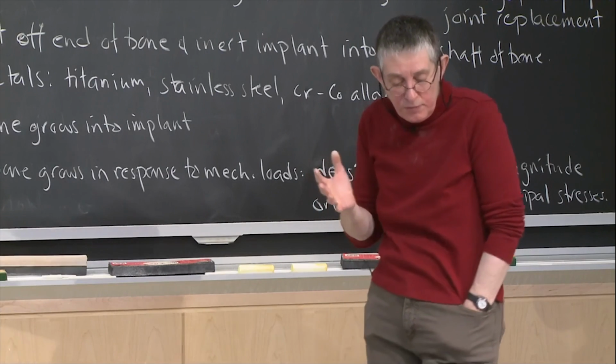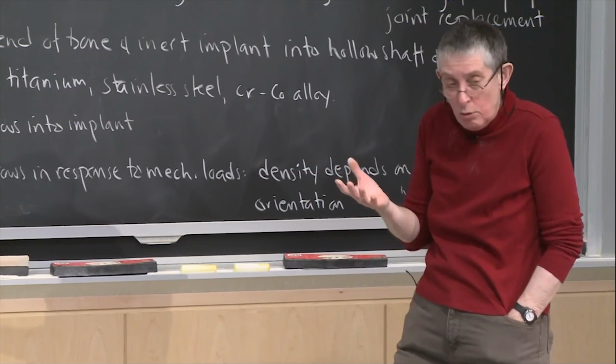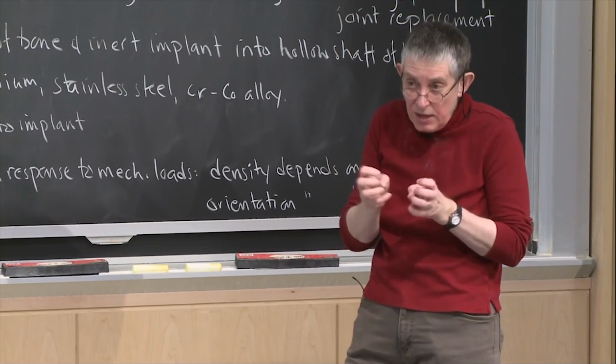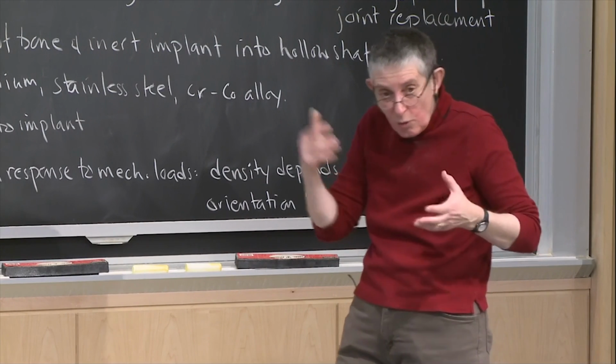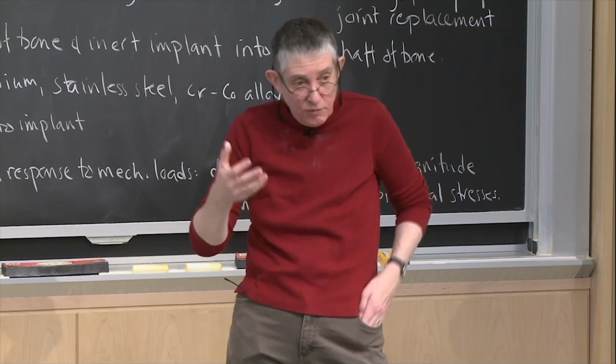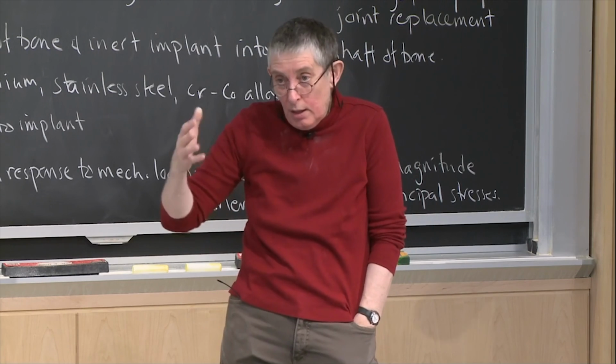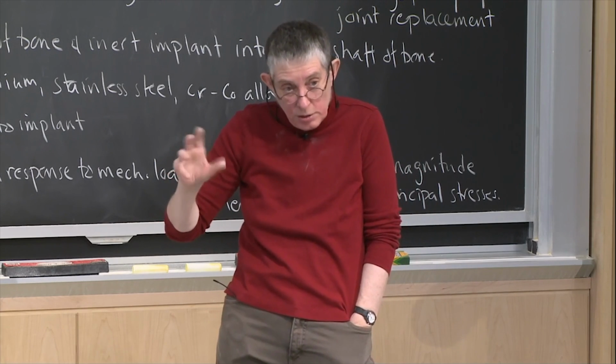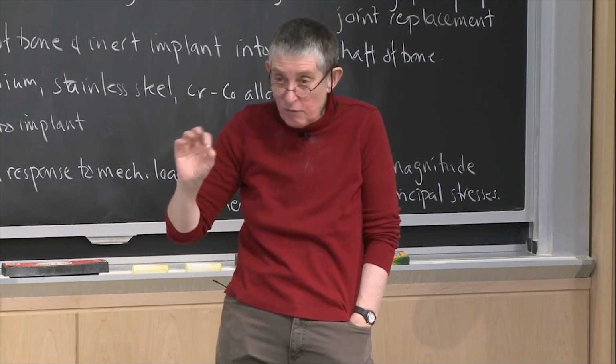And you can think of, from a mechanical point of view, if you lose density by thinning the struts, you can use our foam equations and say the density went from 0.2 to 0.1, and make some estimate of how the modulus and the strength would vary depending on our foam models.